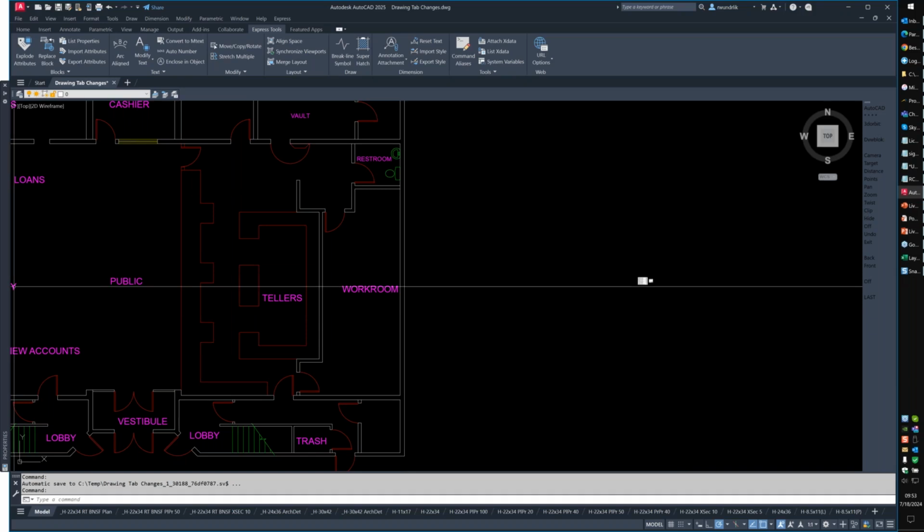Best scaling tips for PDF underlay that does not have OSNAP grip options? That means you're bringing in a raster, and your best bet is to pick the center of the rasterized line.